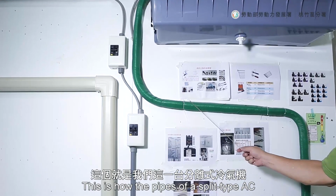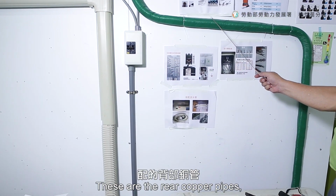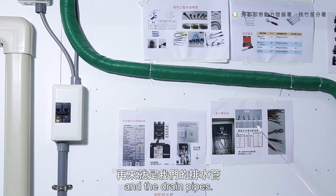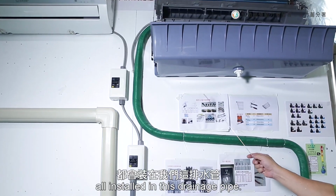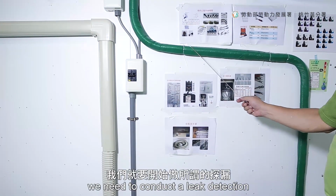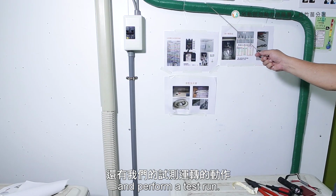This is how the pipes of the split-type AC are arranged during installation. These are the rear copper pipes and the control wires and power wires and the drain pipes. So inside here, there are copper pipes, water pipes, and wire, all installed in the drainage pipe. After we've installed everything, we need to conduct a leak detection and perform a test run.